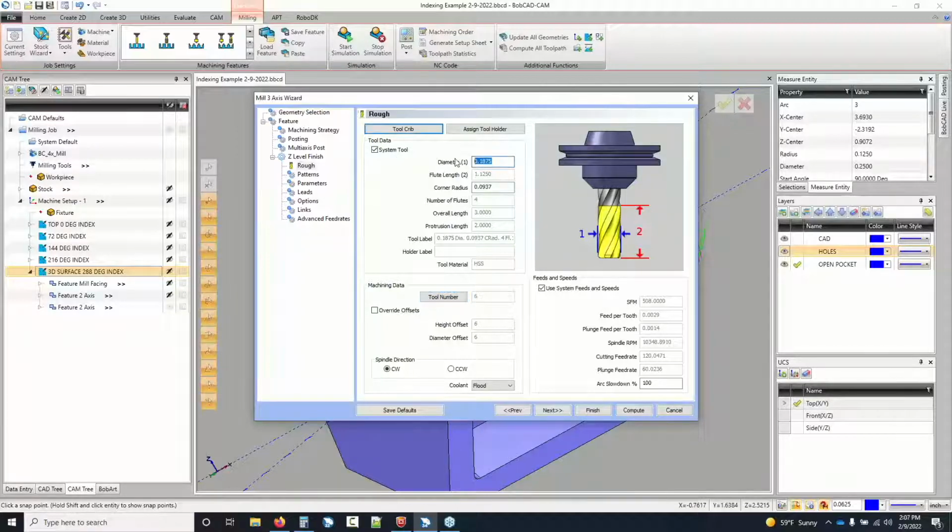The best example is a 1/16 of an inch tool. When I do a 1/16 of an inch, what I need to type to get the corner radius to come out properly is 0.03125. The problem is a lot of guys don't write that. They go out there 4 places, so they put 0.0313, which is not fine.